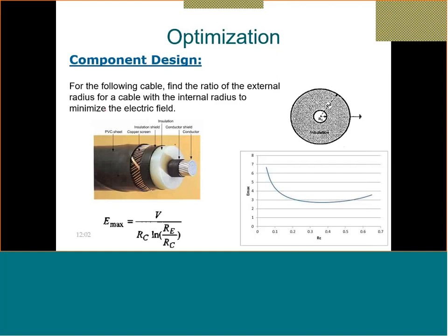You will find that some of those poles have a transformer connected, and this transformer is used to step down the voltage from that level, which is usually around 22 kilovolts or 13.8 kilovolts or 11. There are different voltage levels in different systems. This voltage level is very high, so we step it down to the 120 volts we use in our houses.